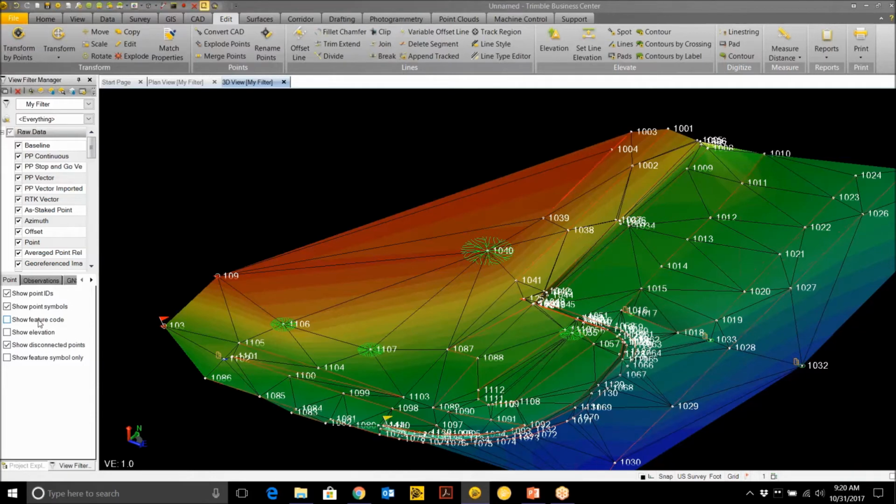And when you exported your DWG, you have the options to export only line work or only the TIN mesh, or you could export everything, correct? So you could select certain objects that are in TBC to export if you only wanted certain things to go. Is that correct? Correct. You could break it down. We could break it down to what is in our project explorer, to what we saved as.